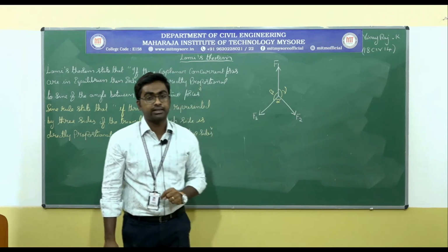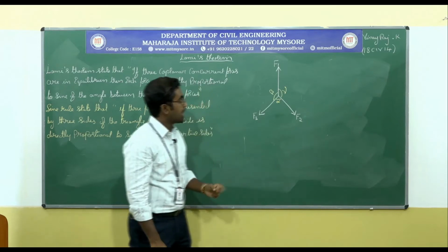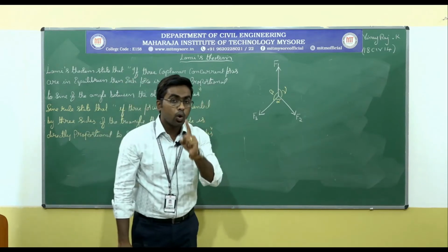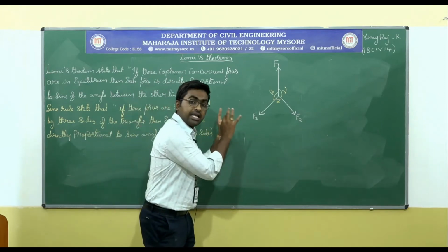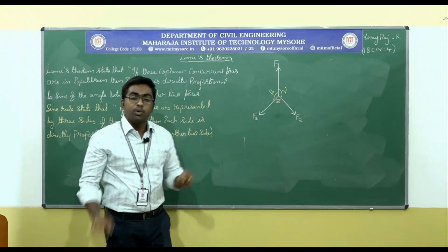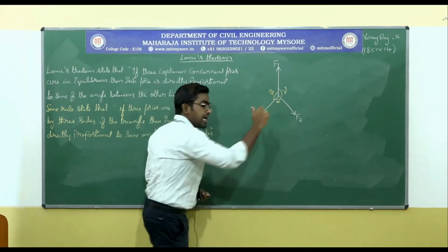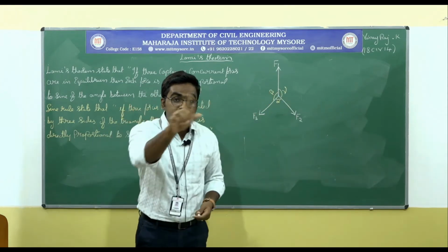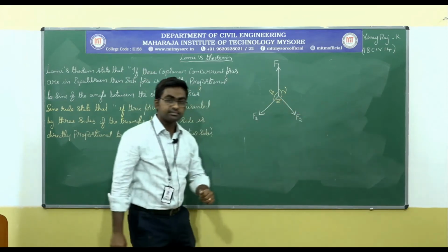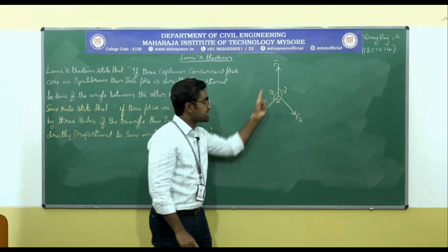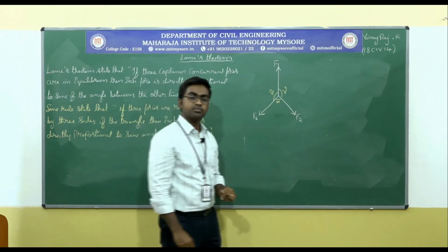It is very, very important. You should not change the angles in the figure. Okay? Next. So these are the three coplanar concurrent forces, and very important is that this system is in equilibrium. When three coplanar concurrent forces are in equilibrium, then these three forces can be represented by the sides of a triangle. That's what I am going to do in the next figure. I am going to represent these three forces in the form of sides of a triangle, right?